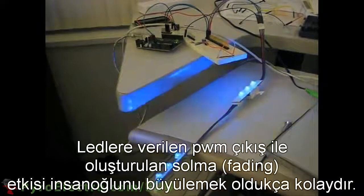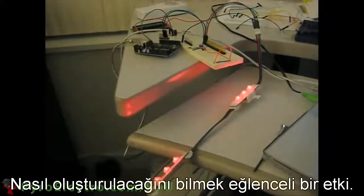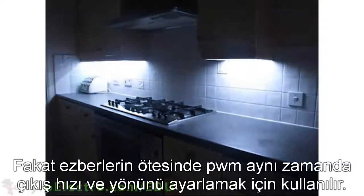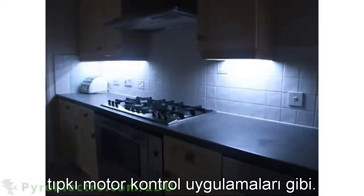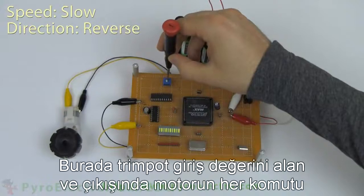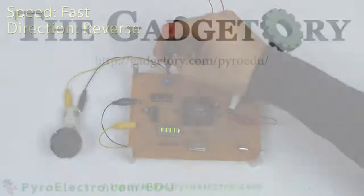The fading effect created by outputting PWM to LEDs mesmerizes human beings quite easily, so it's a fun effect to know how to create. And we've all seen it somewhere in our everyday life. But beyond mesmerization, PWM is also used to output directional and speed data, like for motor controller applications. Here you can see a CPLD that is taking trim pot input data and outputting it as a PWM signal to a motor controller, making the motor obey its every command.